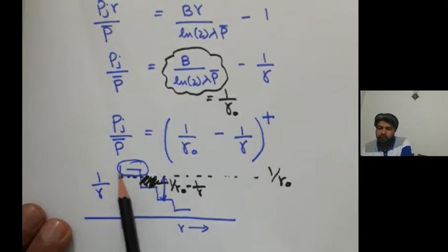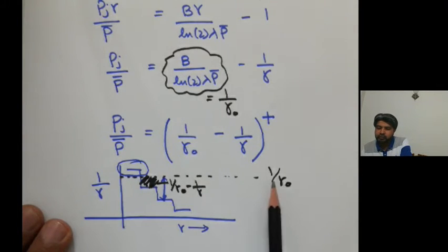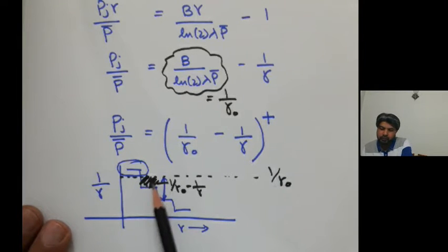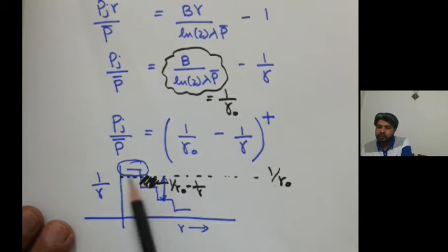So we plotted 1 over gamma with respect to gamma on this axis. If we have a discrete time channel, as gamma increases, 1 over gamma would decrease, so you have this kind of a decreasing function. This 1 over gamma curve can be thought of as the base of a container, and then you have a fixed water level, which is 1 over gamma naught. So you need to put in water. By water, we mean the power we are going to put in until we reach this 1 over gamma naught, which is your water level.